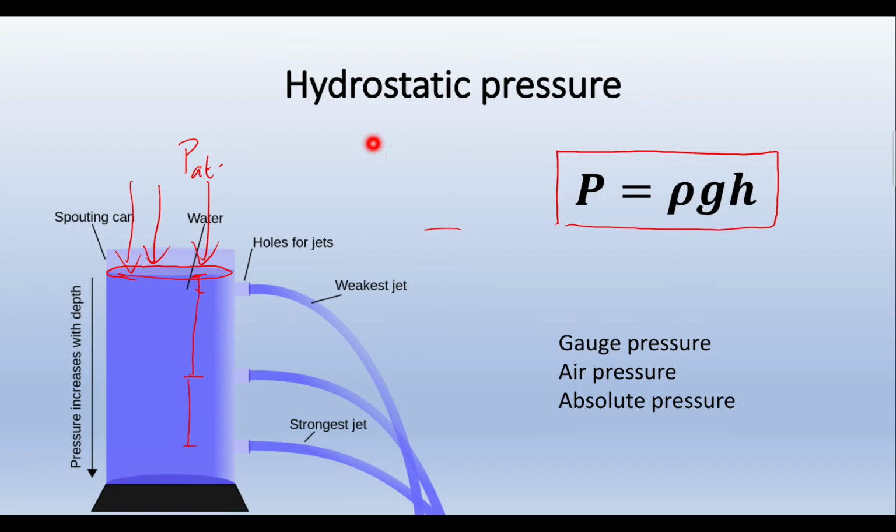So what is the pressure that we are measuring? The pressure we are measuring because of the liquid in different layers is the so-called gauge pressure. The pressure due to air, or the atmosphere, on the top surface is the atmospheric pressure. And when we add them both together, gauge pressure and atmospheric pressure, we get absolute pressure. I'm sure you already know about this from thermodynamics, but I just want you to remember, because this is quite an important thing, my dear people.